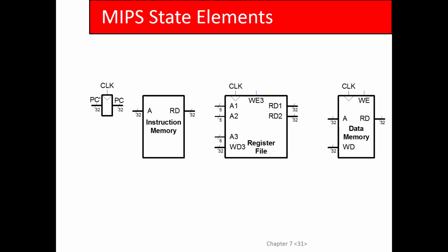So they're not different. It's a little bit misleading. You might ask, is this a different memory space than that? Like if I write address 0 on this guy, and read address 0 on this guy, is that the same data I'm referring to? Yes, because it's one unified address space.